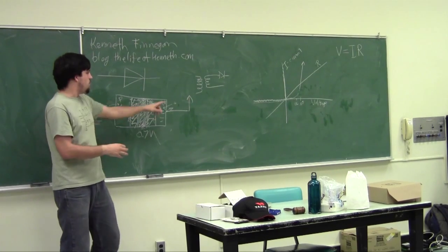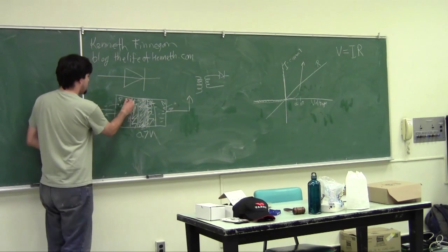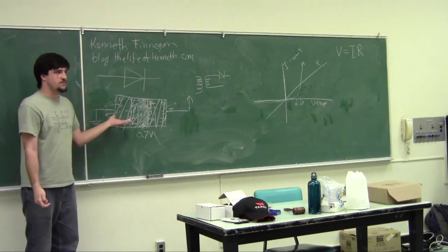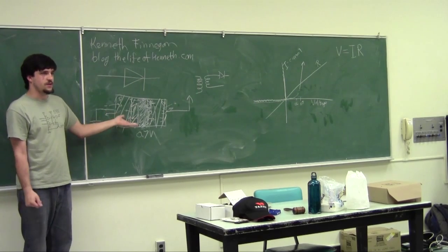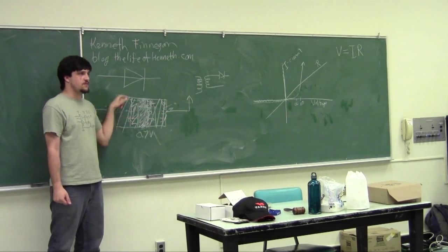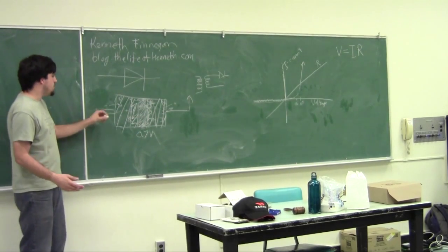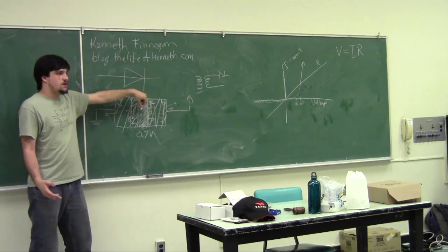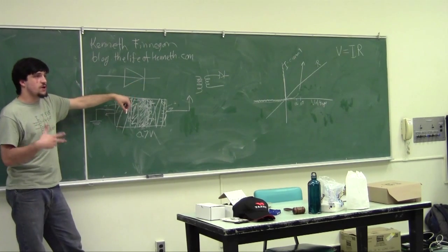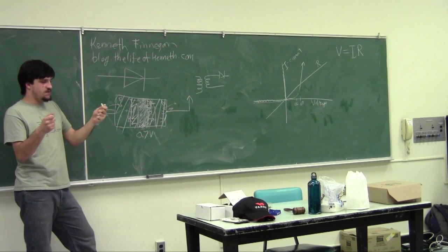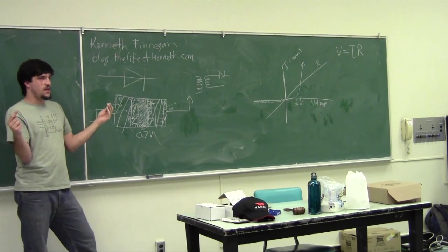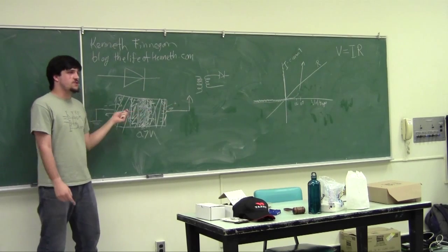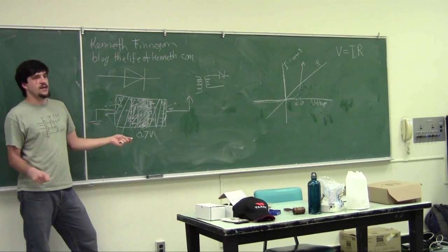Of course, if we keep applying a larger and larger reverse voltage like this, eventually the entire semiconductor gets depleted, and we instead just have a piece of silicon, right? We're talking on the order of microns here. This is a tiny square that I'm drawing for you guys, because I don't happen to have a good microscope, so I'm not actually going to show it to you firsthand. Once you reach this point, the diode is eventually going to break down. Because just as you can take very, very high voltage and get it to arc across air, because even though air isn't a conductor, you can make an arc in air, you can eventually, with enough force, pass current through this. And this is called the reverse breakdown voltage of the diode.